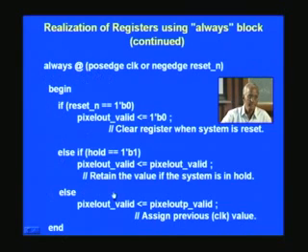And especially when you want to redesign something or even start on a new design, all you need to do is just save your earlier project's file and simply rename it to suit the new design. So that way it helps. And second thing is, you are not bogged down by so many details, so many signals. What I have observed over the years is a number of designers putting hundreds of variables in one always block, and the result will be chaos, and you will get drowned in the myriads of signals, so avoid that.